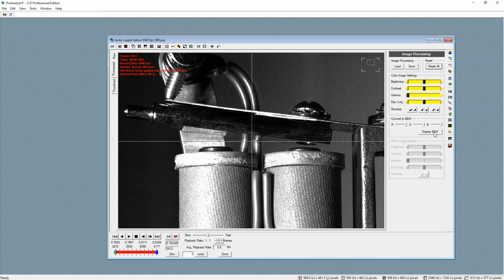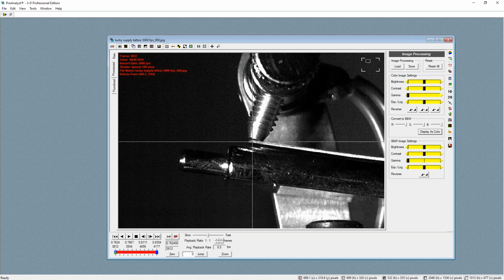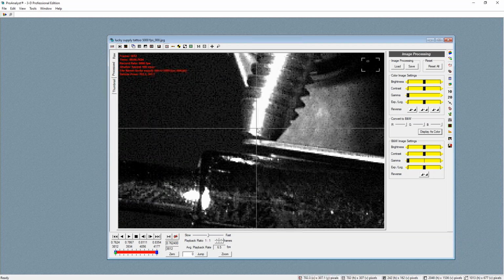So with that done, we want to take this beautiful video and distill it down into the motion that we're looking for. I'm going to put a 1D line tracking from this point down to track and follow this object right here. Then we'll set the value of that as 0, or touching, and as it comes down here, it'll be greater than 0, or not touching.